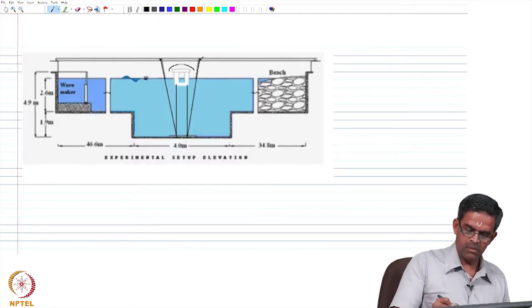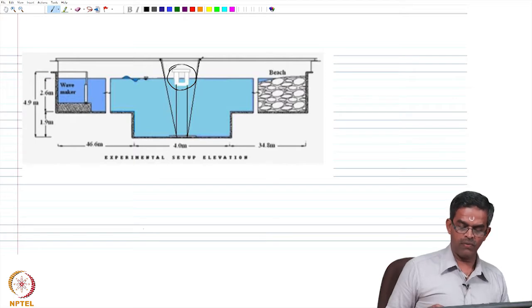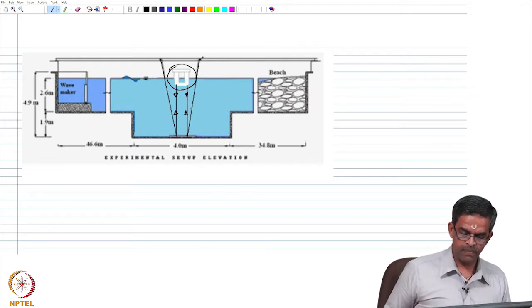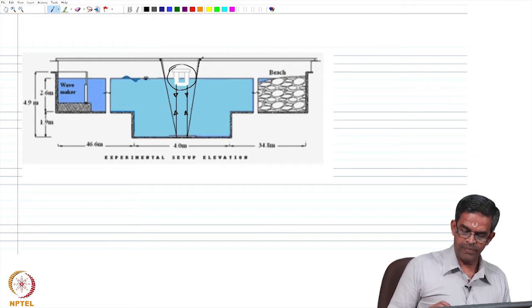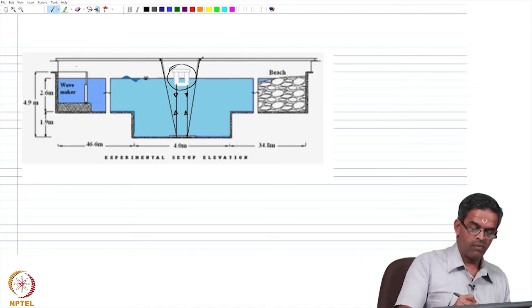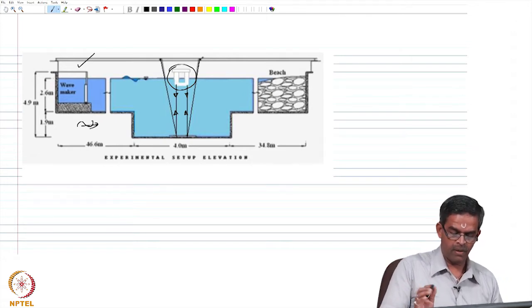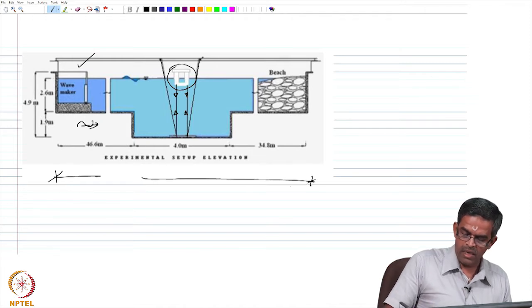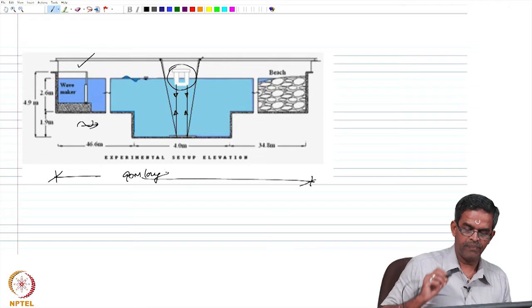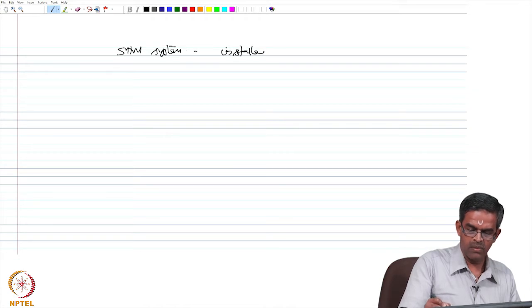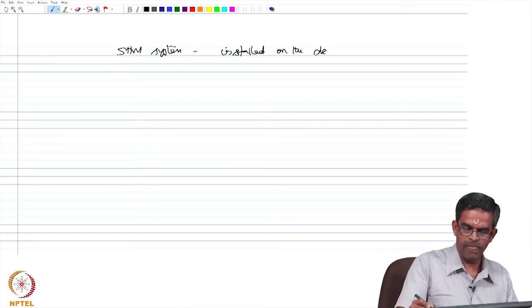The model is installed in the deep water wave flume, as the tethers are subjected to axial tension. It is in the deep water pit, which is about 4.5 meters. From one end the wave is generated and at the other end the wave is absorbed at the beach end. It is approximately 85-90 meters long. That is the test bed, which we discussed earlier as well, installed on the deck of TLP on the lab scale.